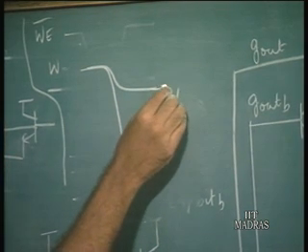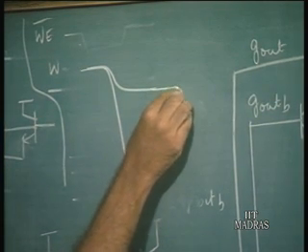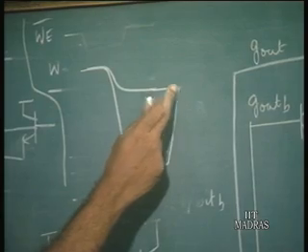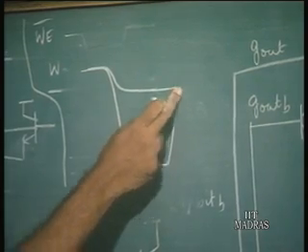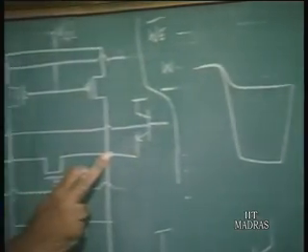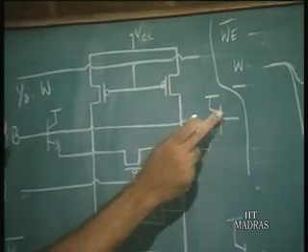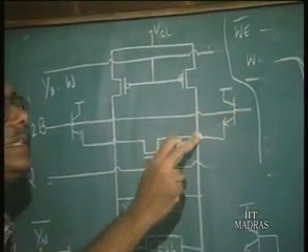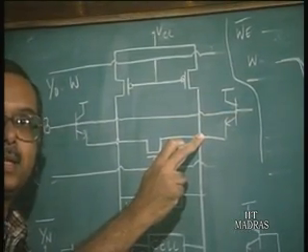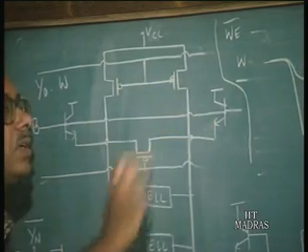Okay. And then what happens is the bipolar transistor can only pull it up to VCC minus VBE, because once this line goes to VCC minus VBE, and since the base voltage is VCC, then this bipolar transistor can no longer pull it up because it turns off.